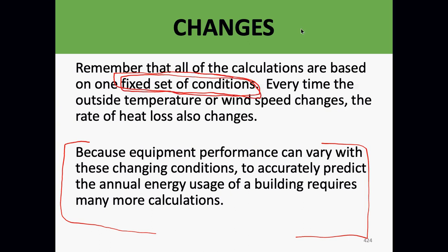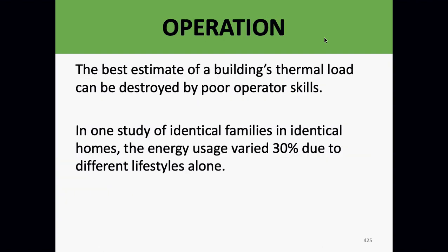Okay, look at wind speeds. If you're on the top of a ridge or halfway up a mountain someplace, your wind speeds are going to be higher, so you probably want to go a little bit more extreme on your temperatures and on your infiltration rates, which we're going to talk about today. Any questions on that? Okay.